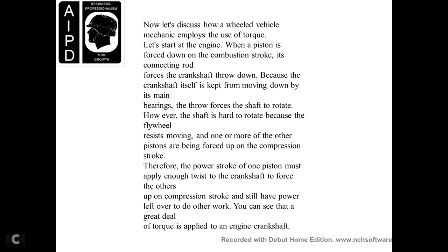Now let's discuss how the wheeled vehicle mechanic employs torque. Let's start with the engine. The piston is forced down on the combustion stroke, pushing the connecting rod. The crankshaft throw goes down, but because the crankshaft is kept from moving down by the main bearing, the throw's force is applied to rotate the shaft.